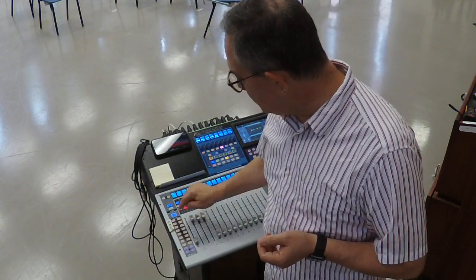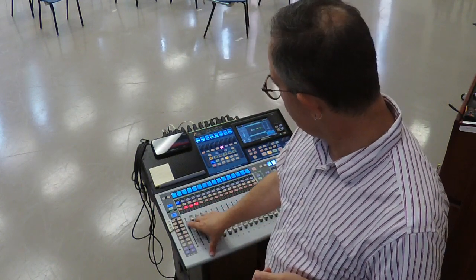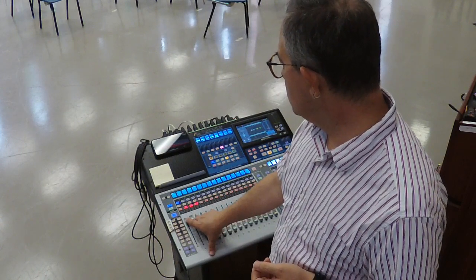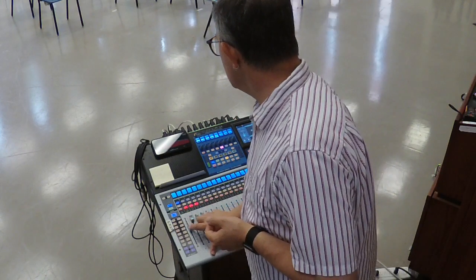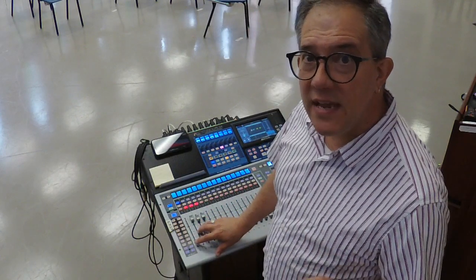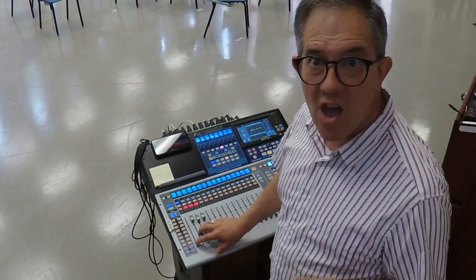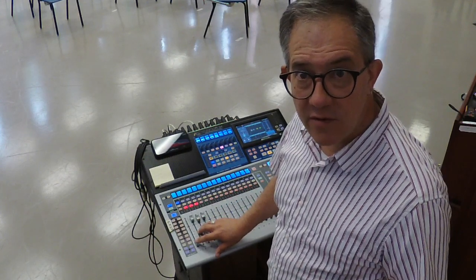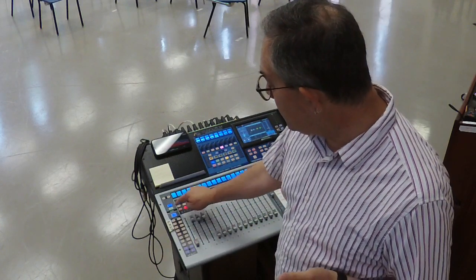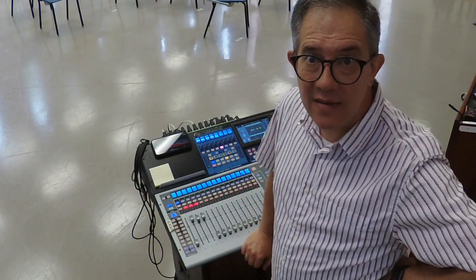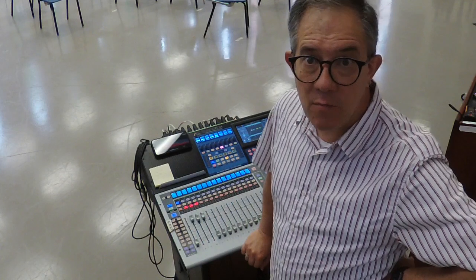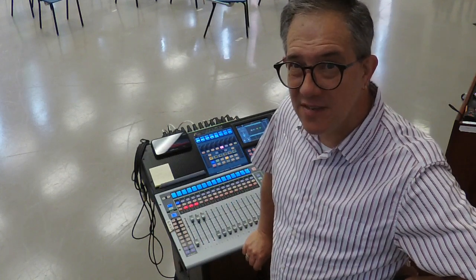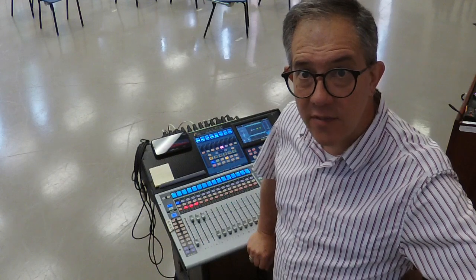So I'm going to turn on the first microphone to the left. So my RTA is telling me that low frequency that's ringing is 147 hertz. So I'm actually going to use some EQ to take that particular frequency out. While I could do it on the input channel, it's not the most effective way to do it, because there are going to tend to be lots of frequencies that are similar if microphones are in similar positions.